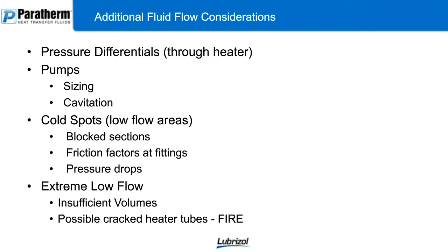And then you really need to worry about extreme low flow. So you have insufficient volumes. You could possibly crack your heater tubes and cause a fire. That's why flow is so important. Safety aspects, efficiency aspects, and maintenance aspects, everything else goes in with flow.